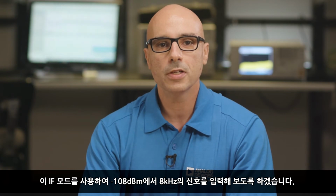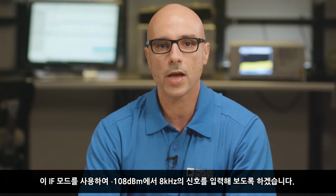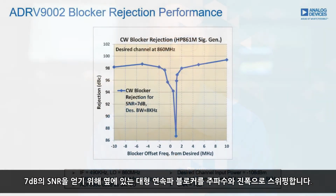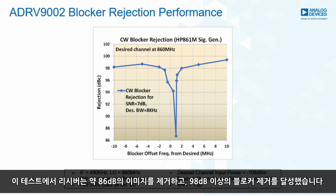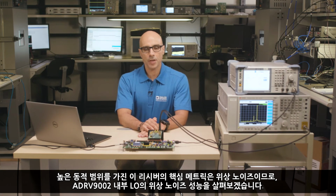Using this IF mode, we are going to input an 8 kHz signal at -108 dBm, and we are going to sweep this large continuous wave blocker next to it in frequency and amplitude to get to an SNR of 7 dB. The receiver achieves in excess of 98 dB blocker rejection in this test, with an image rejection of about 86 dB.